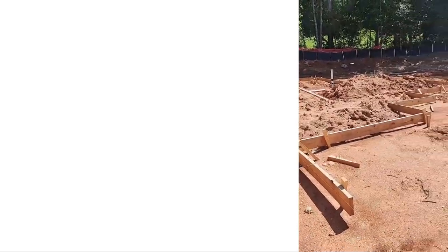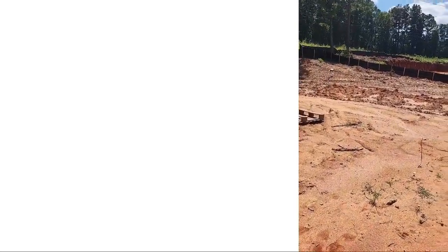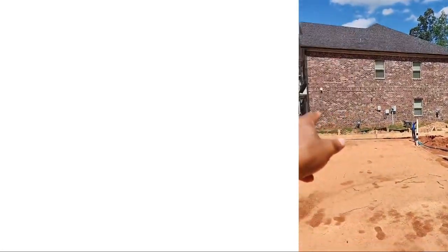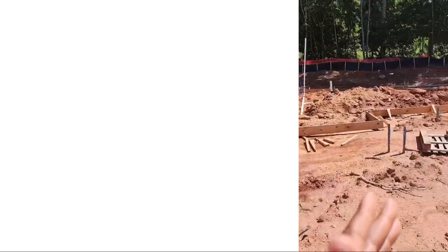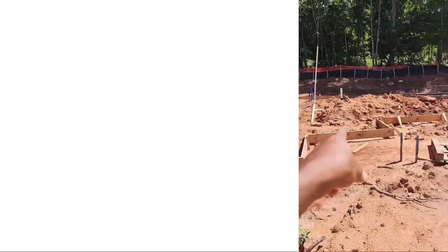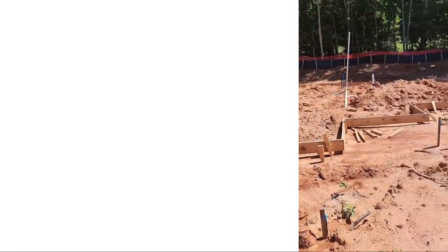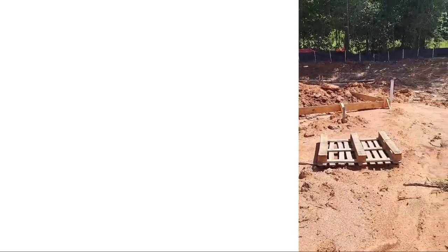All right, so for your site plan, once all the clearing is done, once we put all the erosion control up, the silt fencing, and the construction entrance, once we have all that done, and then we'll grade it out, then they're going to come in and we're going to form the box for the construction area. And then everything moves beyond that.